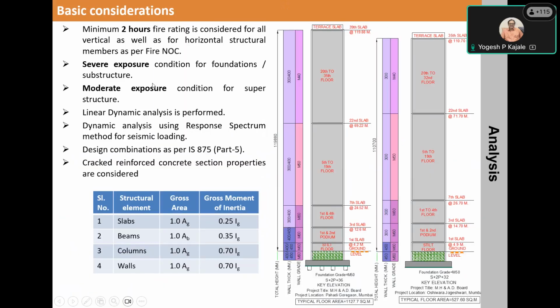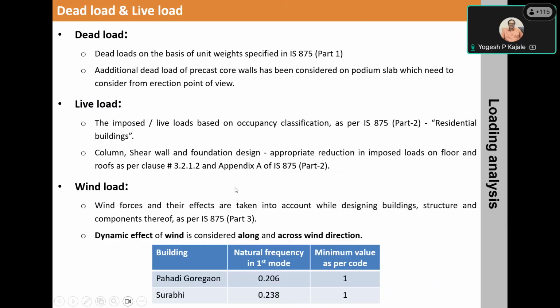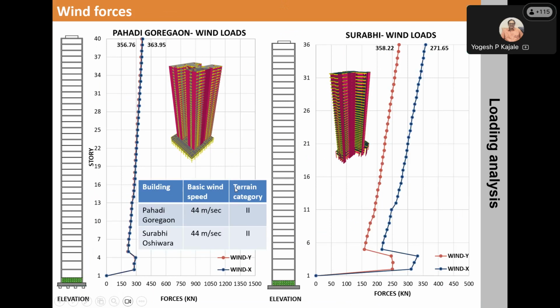See, the elements typically have 2 hours fire rating, severe exposure conditions. These are standard norms as per the Indian standard. All the loading are considered as per the prevailing Indian standards, IS 1893 as well as IS 875. Then the analysis was conducted.